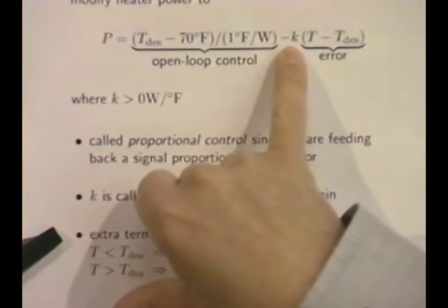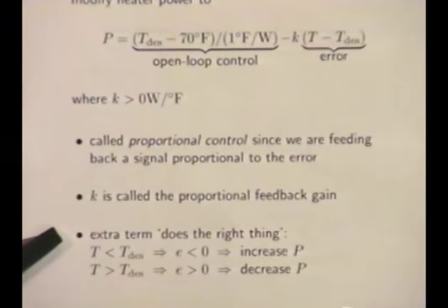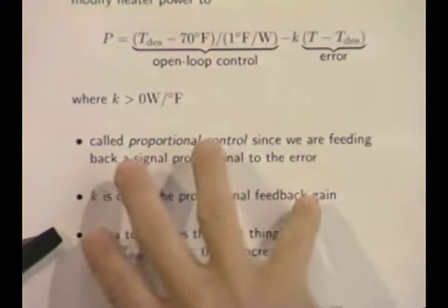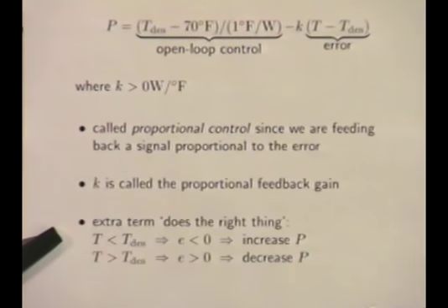And this constant k is a number which gives you kind of, I don't know, how snappy, how aggressive the feedback is. For example, it basically tells you how much power you modify by depending on how much the error is. Okay, so in an aggressive controller here, k would be large. And in kind of a mild one, it might be smaller.